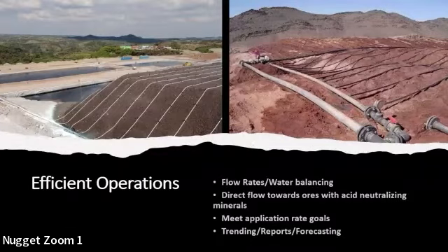Basically, what we wanted was to get as much information as possible, to correlate the information gathered from the CPTU and its interpretations with lab tests, especially the saturation and moisture contents of some samples, and see what the saturation ratio was and whether any issues could raise a red light in terms of static liquefaction.